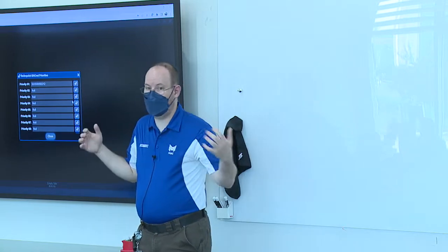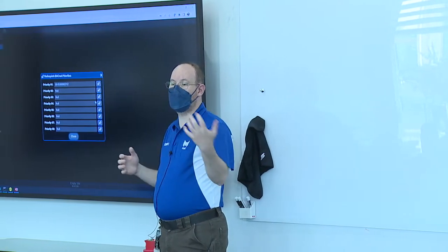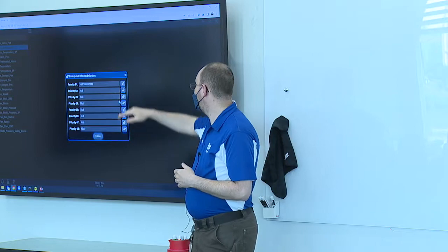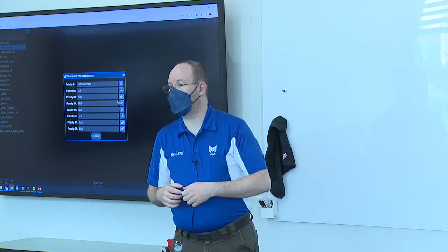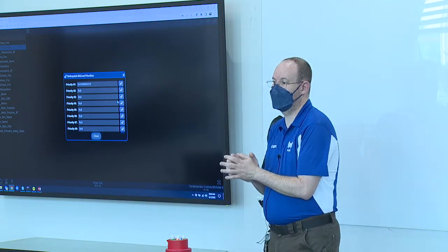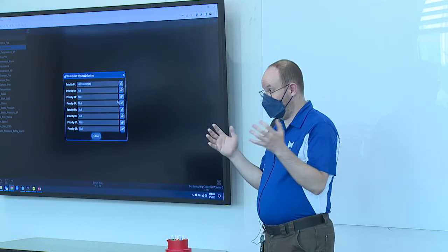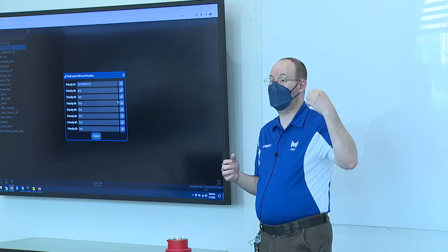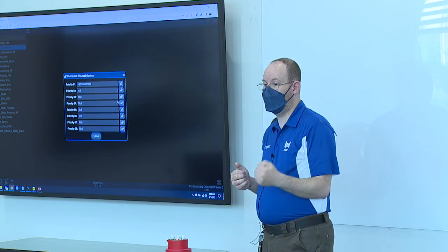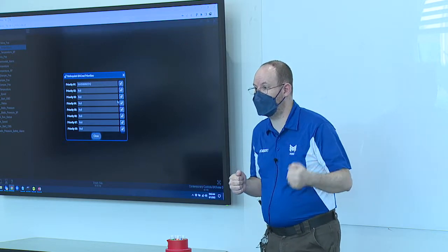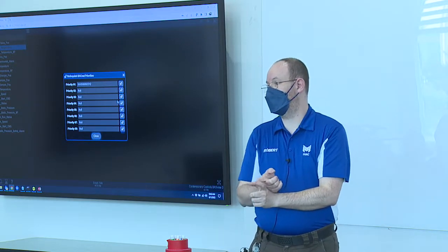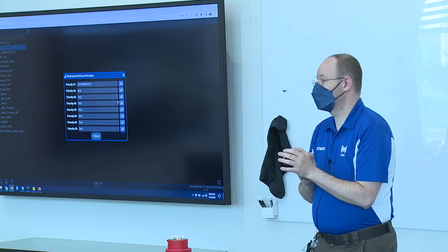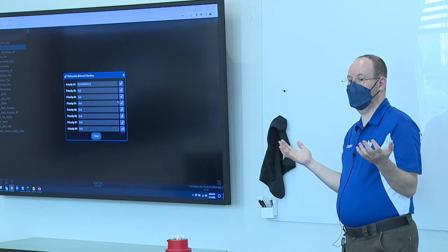Administrator or emergency overrides happen at priority 2. Priority 1 is reserved for life safety. As a rule of thumb, you should almost never be doing something on priority 1 that isn't related to something like a fire alarm. Make sense?